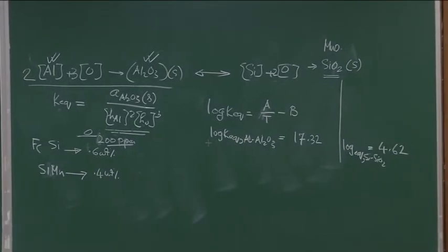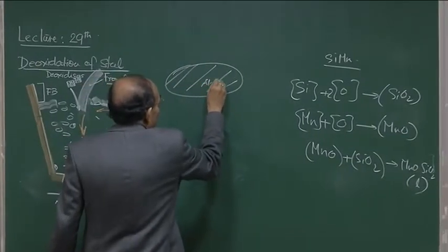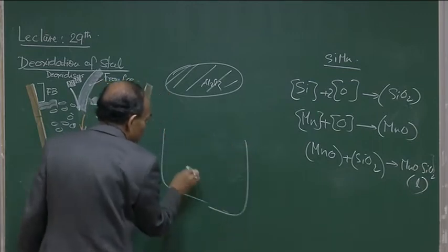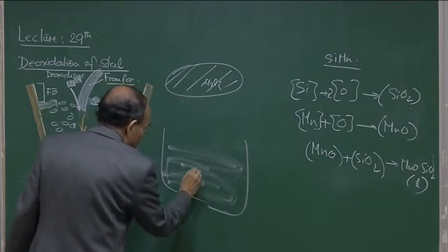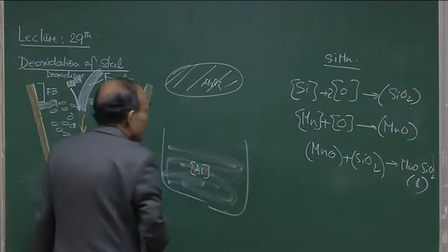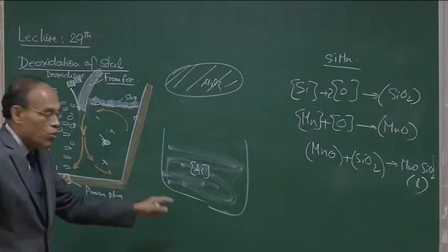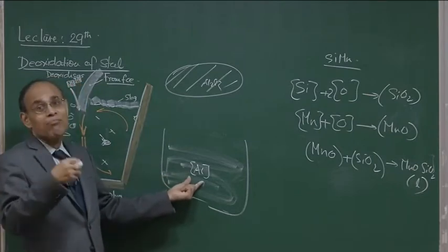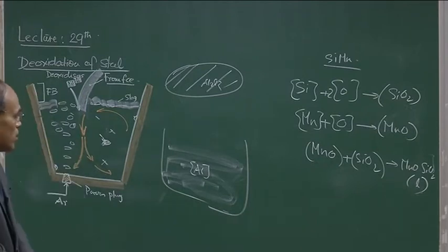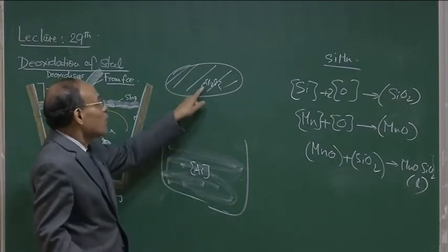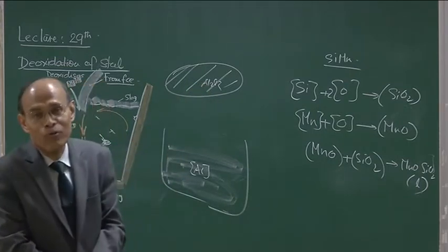Okay. So, if we sum up the oxides, this is the total alumina that has formed, and then we have the metal, homogeneous everywhere, with dissolved aluminum. If you do an aluminum balance, you find out how much aluminum is in the dissolved state by spectroscopic analysis, and how much Al2O3 has formed. The aluminum contained in Al2O3 plus dissolved aluminum, if we add them up, should be equal to the amount of the deoxidizer.